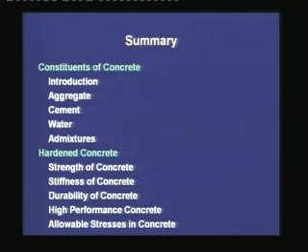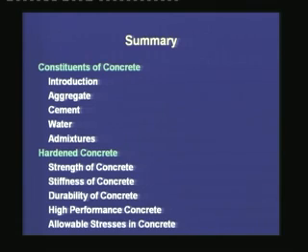Now, in a prestressed concrete member, different types of concrete can be used in the end blocks as compared to the rest of the member. The end blocks are subjected to stress concentration, and fiber reinforced concrete can be used in the end blocks to sustain those high stresses at the anchorage regions. Finally, we moved on to the allowable stresses in concrete.